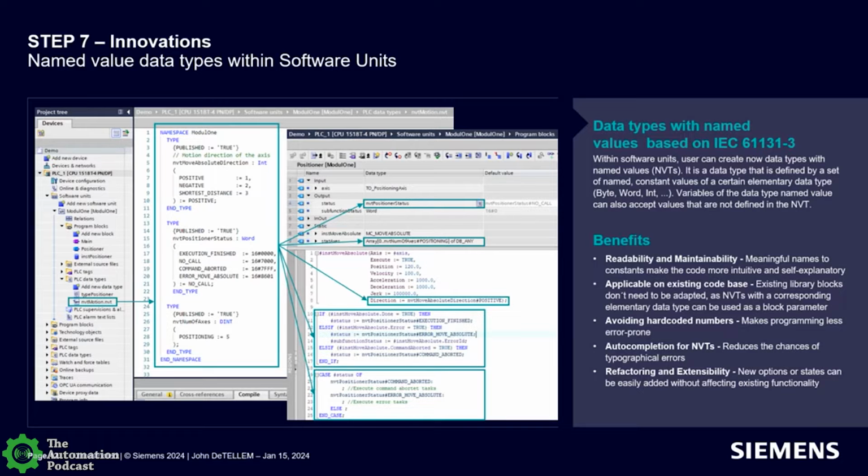Then I can program these independently and download changes to one without affecting the other. Software units have been evolving over the last few years with more functionality to help the user apply this concept. It has to be planned out in the beginning: my mainline stations under a unit, failsafe completely separate, and the robots, the conveyors, the tanks could all be individual ones.